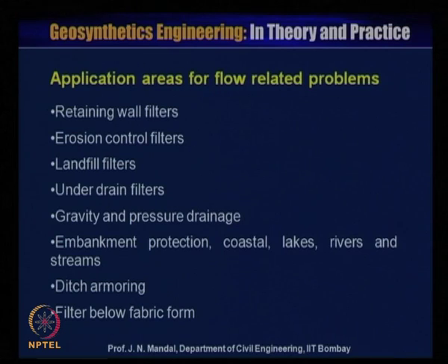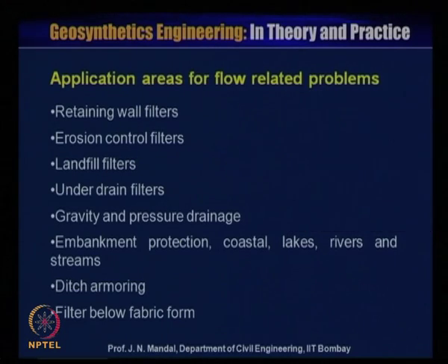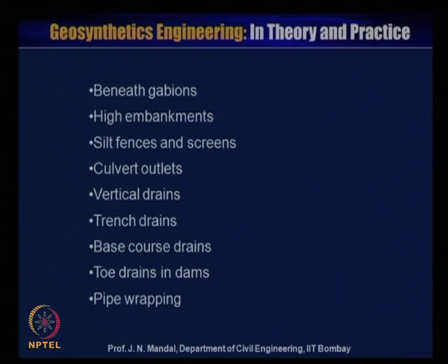The application areas for flow-related problems are retaining wall filter, erosion control filter, landfill filter, underdrain filter, gravity and pressure drainage, embankment protection, coastal, lake, river and stream, ditch anchoring, filter below fabric form, beneath the gabion, high embankment, silt fences and screens, culvert outlet, vertical drain, trench drain, base course drain, toe drain in dam, and pipe wrapping.